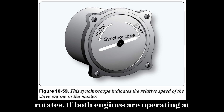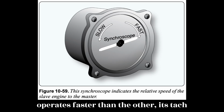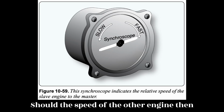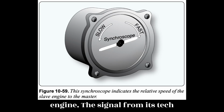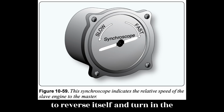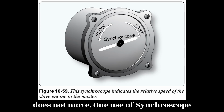If both engines are operating at exactly the same speed, the synchroscope motor does not operate. If one engine operates faster than the other, its tach generator signal causes the synchroscope motor to turn in a given direction. Should the speed of the other engine then become greater than that of the first engine, the signal from its tach generator causes the synchroscope motor to reverse itself and turn in the opposite direction. The pilot makes adjustments to steady the pointer so it does not move.